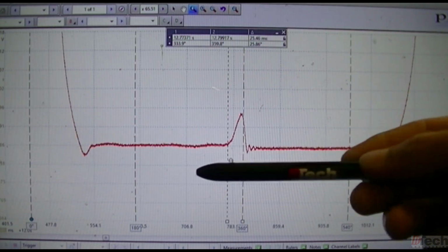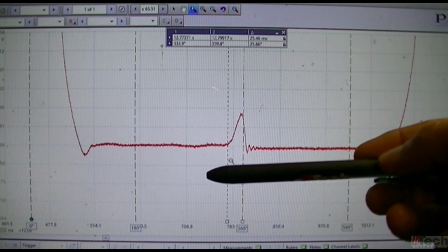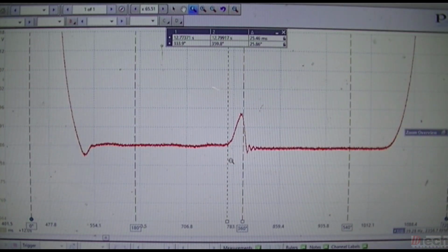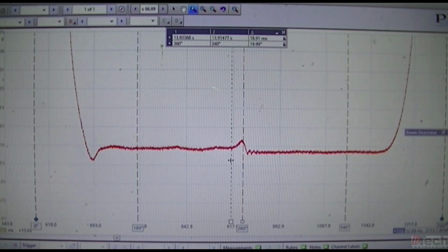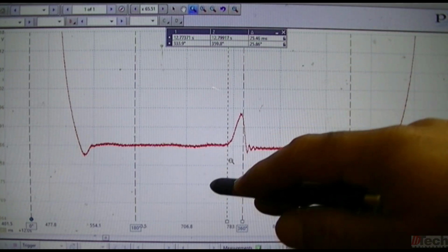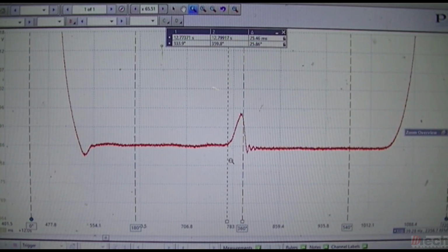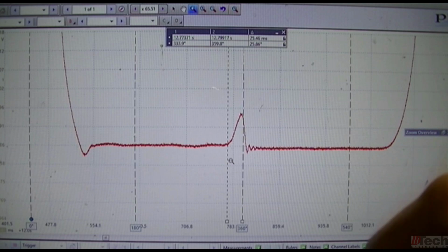Bank 1 happened earlier, closing about 5-6 degrees sooner than bank 2. That's where the higher blip, higher pressure, more time as the piston travels. That's why you're reaching a higher pressure point, because it closed earlier.